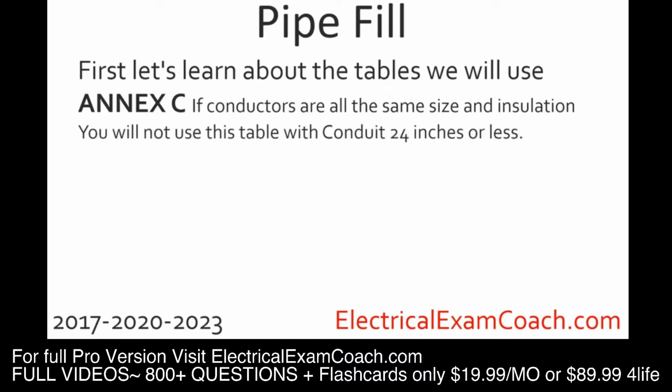You will not use this table if the conduit is 24 inches or less. Now the code book uses the term nipples, but I want you to imagine in your mind, anytime the conduit is 24 inches or less, you're not going to use Annex C. You're going to use the method that I'll teach you in lesson 7.2.